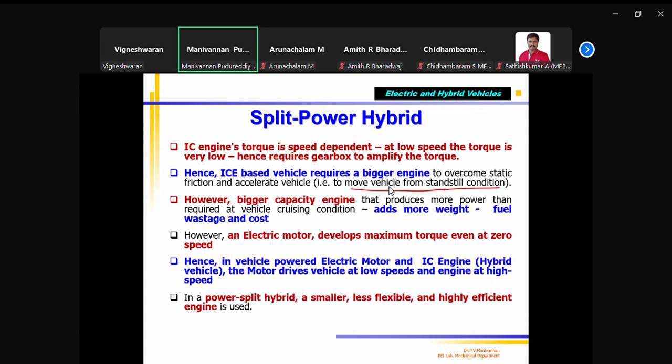Now, without pressing the accelerator, if you release the clutch fully, the vehicle will jump and stop, because sufficient torque is not available to overcome the static friction of the stopped vehicle. You will be doing this many times. Otherwise, your friend or the instructor will say, don't do it, press the accelerator, then release.